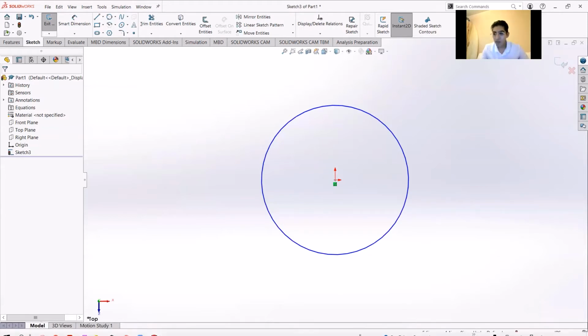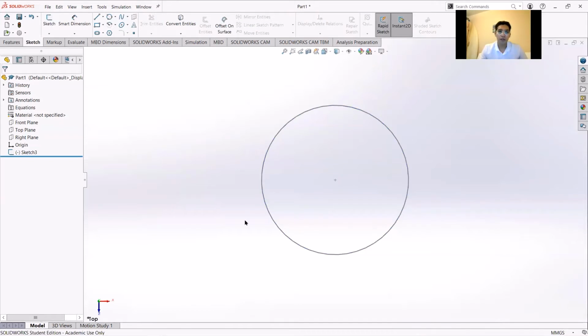So to change that, what we do is we go down to the bottom right over here where it says IPS. There's a little button, and you click on the button, and there's these options. And what we're going to use is millimeters, grams, seconds. So you click that, it'll take you out.